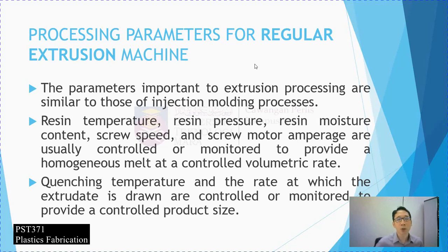Okay, as we know, the extrusion machine produces a continuous product, and for some extrusion machines the die size of the profile does not meet the final requirement, so you require stretching, the draw speed, to provide the required dimension, thickness, etc. Okay, this is where the parameter that I previously mentioned, speed, plays an important role.